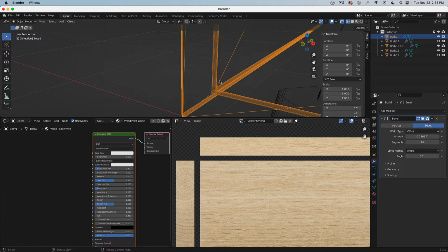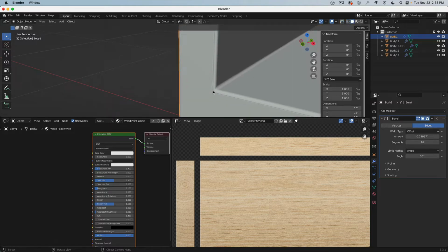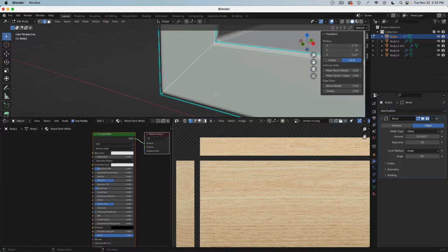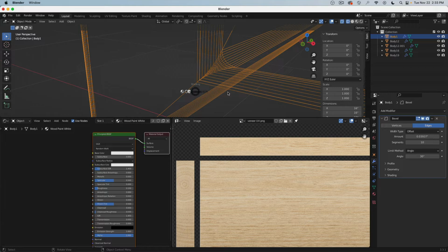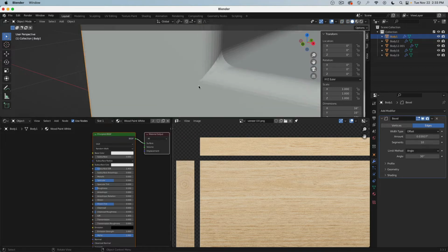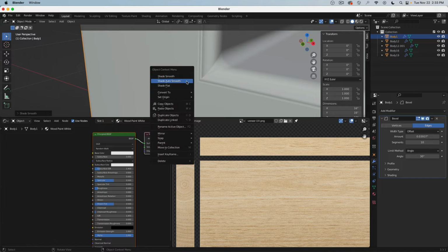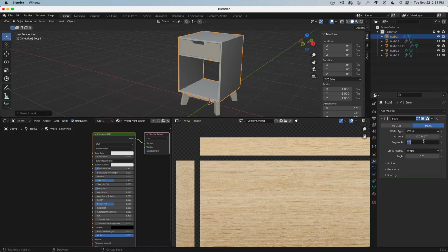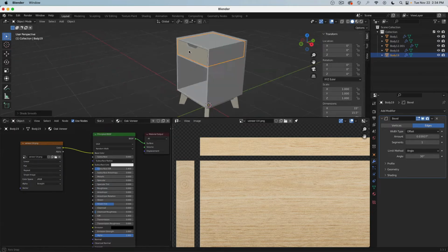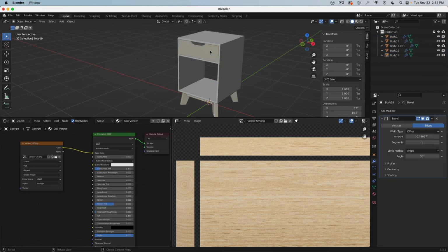There can be issues where there are self-intersecting issues, and we notice here there's something happening. Or maybe this is just only a shading. Right click, yeah, I think it's just only a shading. Yeah, it's not super good for the rendering, it's fine. Again, this is just a little bit of trickery. I go back with 1, right click, shade smooth, with auto. There we are. Okay. It will just look in the rendering nicer when these edges aren't super sharp, but there's a tiny highlight on it.